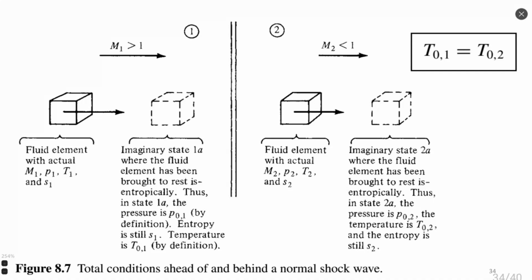Why does stagnation temperature stay the same? Because we do not have any consumer of energy, of thermal energy, in such a system. We do not have a body to have heat transfer or intensive heat transfer. We just have transformation, right? So total temperature is not consumed, even when entropy is changing, total temperature stays the same. It's proven in the theory of gas dynamics, and Anderson showed this by several examples.